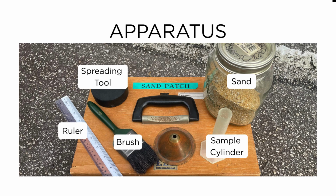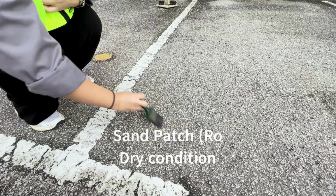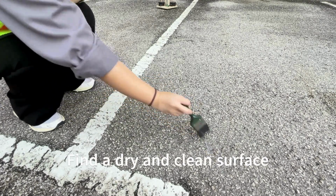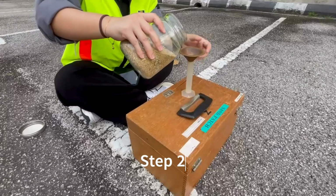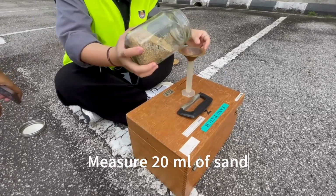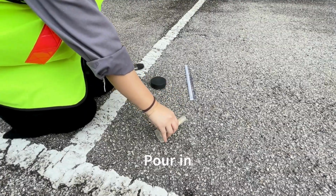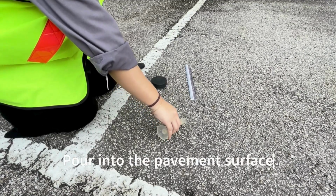The apparatus used in the sand patch method are a spreading tool, ruler, brush, sand, sample cylinder and water. Sand patch, rough surface, dry condition. Step 1. Find a dry and clean surface. Step 2. Measure 20 milliliters of sand. Step 3. Pour it onto the pavement surface.